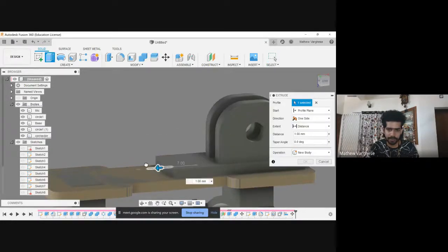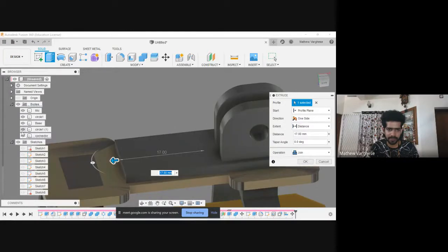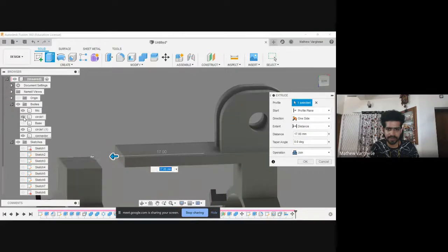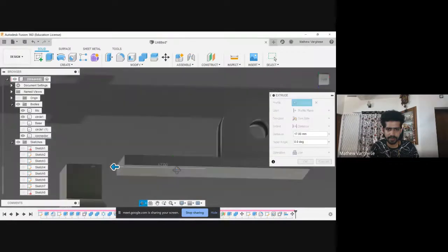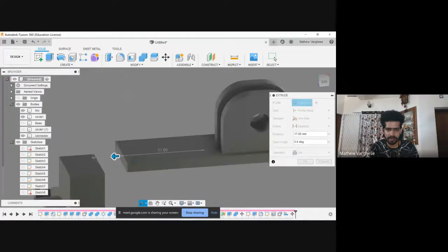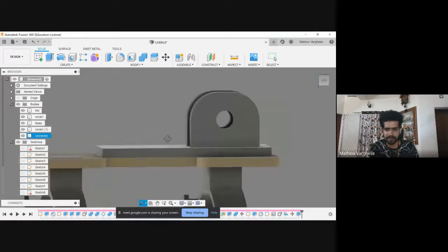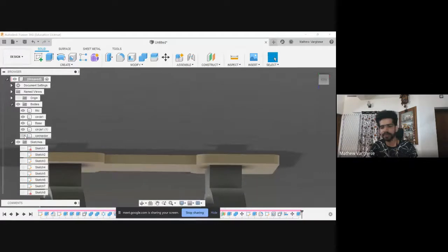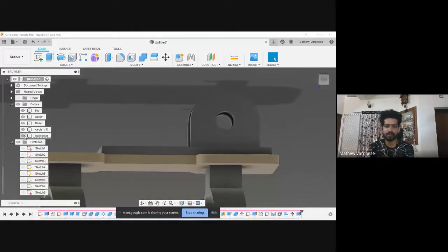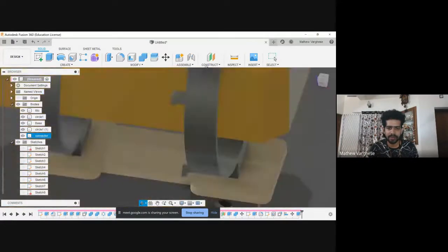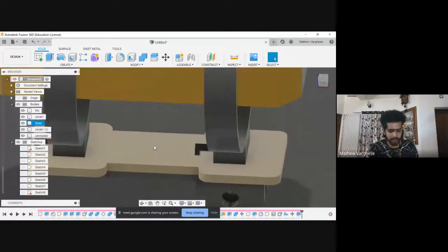And in order to put a screw, I need to extrude it here, right? I'll be switching off the base and circle because we don't want to mess up joining with that. So it is there, and we'll be re-enabling them. Fine. Otherwise it will join to the whole body, and we cannot separate these parts for 3D printing. And there's only one more thing left to do: put a hole through here.